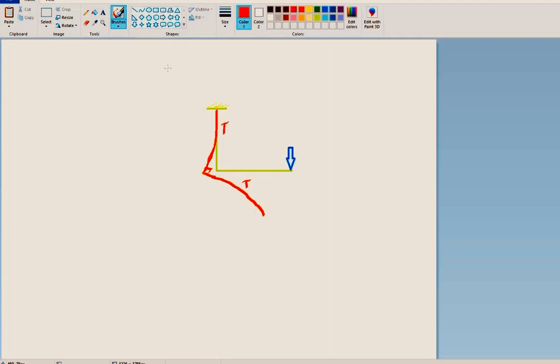Okay, so the bending moment diagram, if we see it while drawing the bending moment diagram, it will look like this. From this point, the load acting at this point, the moment, force into distance, is 0. At this point, if we see force into distance, that will be the moment. It will be linearly varying like this. This is the bending moment for this beam, and for this point, if we see the force into distance, that is a moment value, that is tension is this side. And then at this point, if we see, this is the same force, same distance, so even throughout this column, this force into distance is the same.